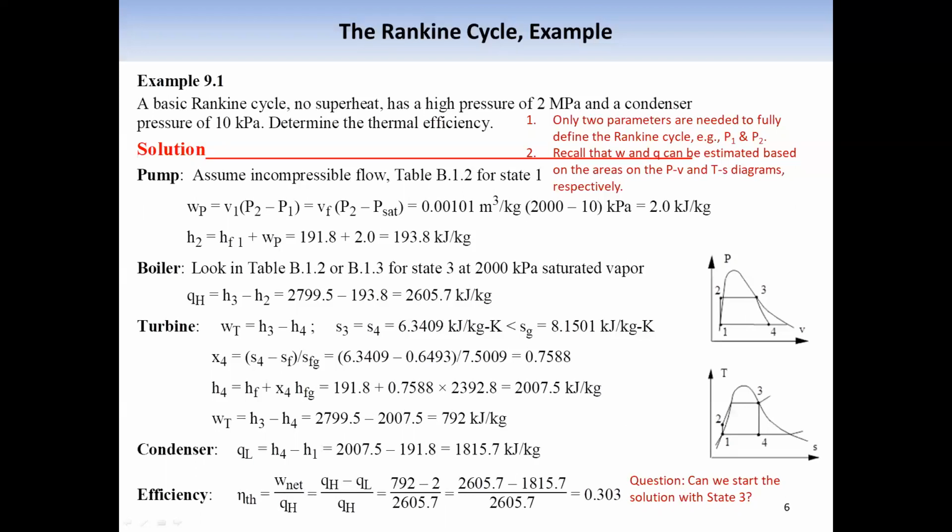Here at the bottom, I'd like to remind you to think about whether we can start from state 3 for the analysis. The answer is yes, because it's saturated steam. The pressure is given, so the temperature is known.